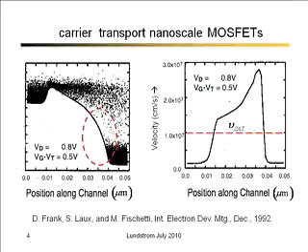When the electric field in bulk silicon gets very high, electrons scatter a lot, and you approach a saturated velocity that's almost exactly 1 × 10⁷ centimeters per second. So if you look at the drain in this simulation, the electric field is very high near the drain end. But if you look at the average velocity, you can see that it's very much higher than that saturated velocity of 1 × 10⁷.